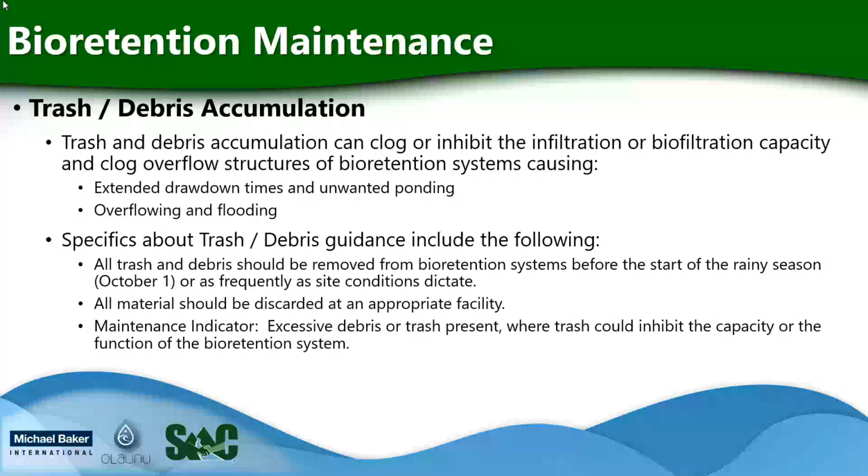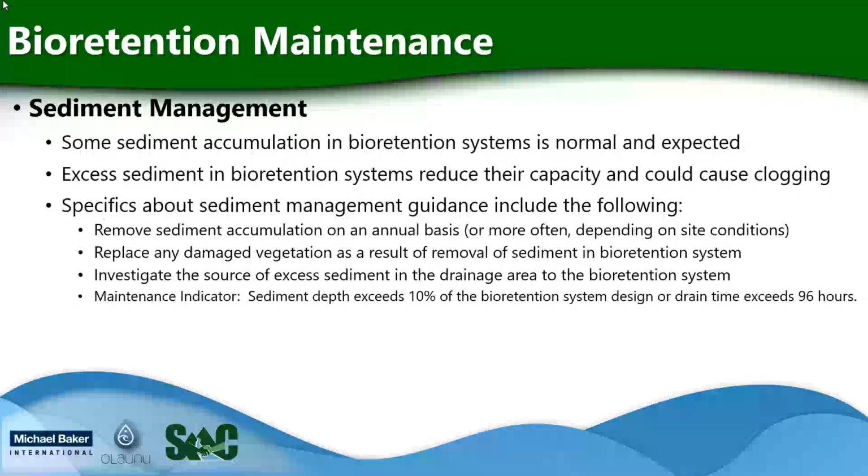Sediment management is also an issue for bioretention maintenance. Some sediment accumulation in bioretention systems is normal and expected. Excess sediment in bioretention systems reduces their capacity and could cause clogging. Specifics about sediment management guidance include the following.